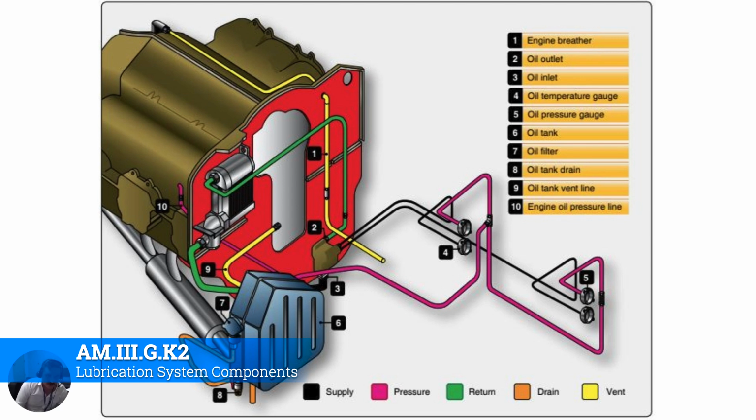Just this particular example is one. Inside the tank, a weighted flexible rubber hose is mounted so that it's repositioned automatically to ensure the oil will pick up during all maneuvers. So as the plane tips and dives and does all kinds of things, that weighted hose follows the lowest point on the tank, which allows the oil to keep on entering the system.